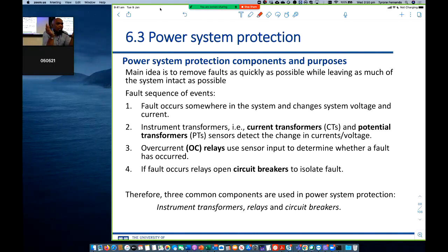Say you're measuring a high current, right? With a transformer, you can actually drop the current into a smaller value. So if, let's say, 100 amps are flowing, you drop to 1 milliamp, for example, using a transformer. That 1 milliamp will then indicate to me, because I know the turns ratio, that it's 100 amps flowing there. Same with voltage.